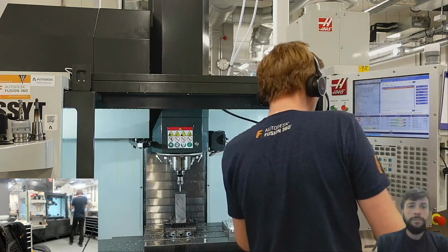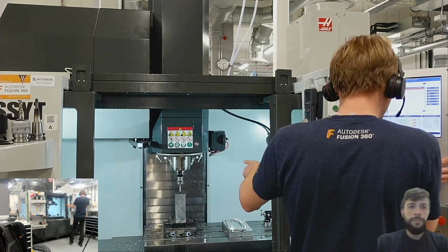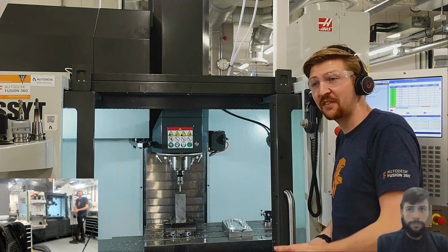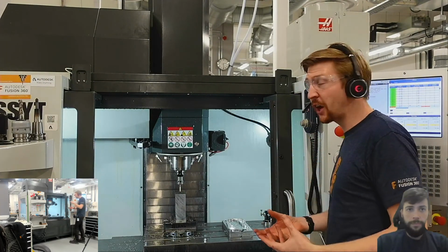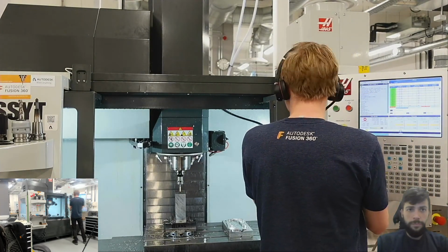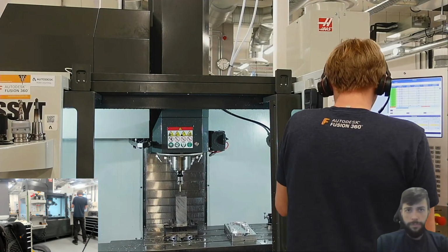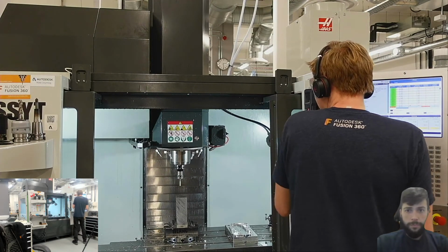So right, what I always do is I would never start the machine like that, because I've seen far too many machines plummet down as the first thing they do. You've got something wrong in the code, and I definitely don't want to plummet down. So we're going to move it over in Y and then up in Z.